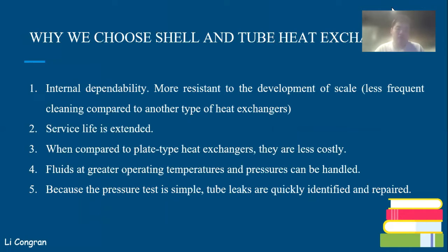So why did we choose the shell and tube heat exchanger? Because of internal accessibility, more resistance to development of scales, like less frequency of cleaning compared with other types of heat exchangers. The service life is extended, and compared to the plate type heat exchangers, they are less costly, and fluids at greater operating temperatures and pressures are easily handled. And last but not least, the pressure test is simple and tube leaks are quickly identified and repaired.